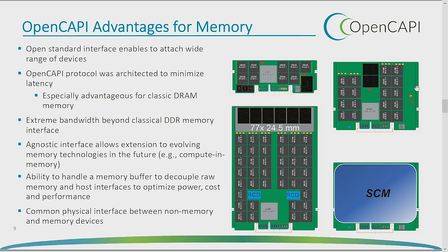So this one, I guess I have a little bit of passion about: memory in systems. The way we attach memory historically in a typical industry system is with DDR memory. And direct attached DDR memory is really a horrible interface. It runs at low frequency, right? If I'm talking about DDR, it's running maybe at 2.5, 2.6 gigahertz. This is an extremely low frequency compared to what we get with differential signaling. In the differential space, we're at 25 gig today. So we're running about 10 times faster device to processor interfaces compared to DDR.